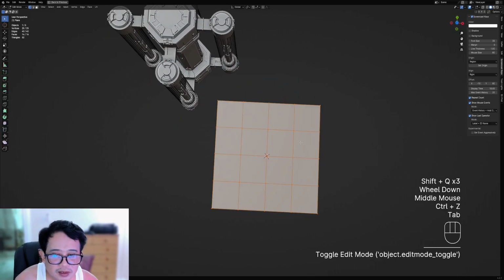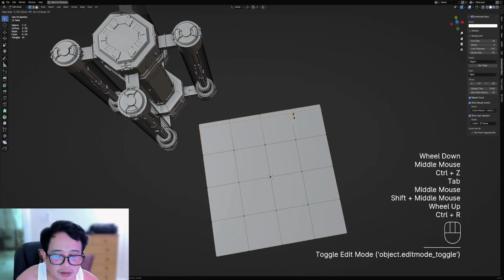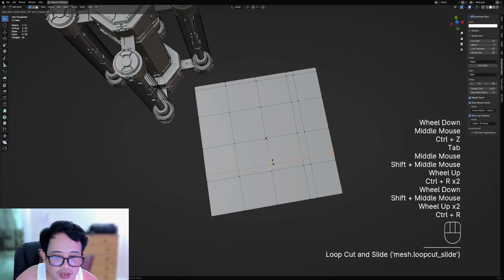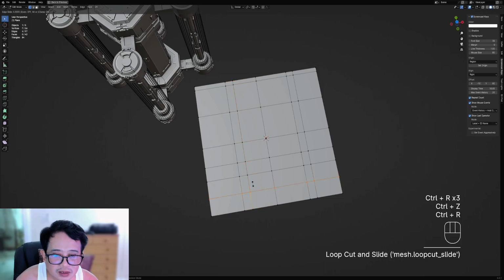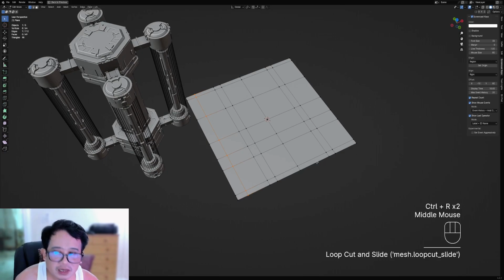But if you introduce some edge loops to the topology, make everything random. Everything has to be quads or tris because the scripts cannot subdivide n-gons. Especially if you make it like that or something like that, most of the details will probably be constricted on those areas.